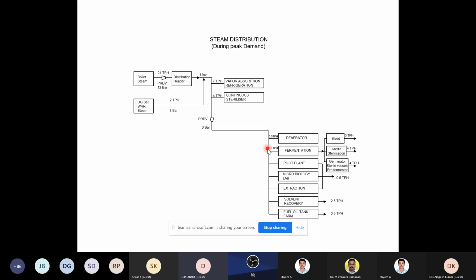Whatever the heat transferred, from that you can find out what is the steam consumption, or you can estimate, or in the worst case also guesstimate, so that you get a fairly decent steam balance. So you should know where to focus your attention, where steam is consumed to the maximum.